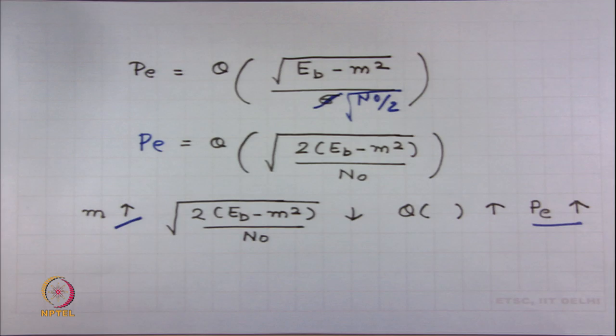However, it was disproved in 1994 by a paper published in Transactions on Communications, and the authors of that paper proved that at ridiculously low levels of signal to noise ratio, there is a constellation system which can achieve a better BER for a given Eb/N0. So, simplex signals are not optimal at ridiculously low levels of SNR, but otherwise they are believed to have the best BER performance for a given Eb/N0, and this is because they have 0 mean.